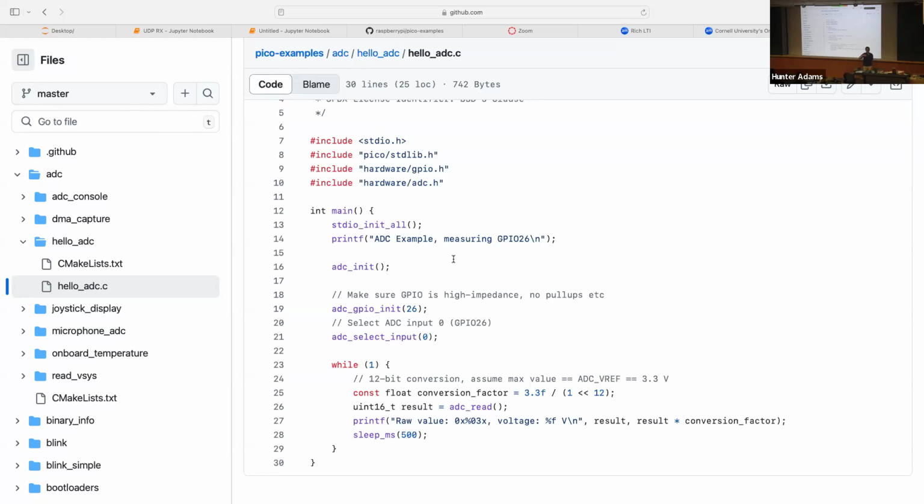And that's sort of expected because remember when we talked about the ADC, one of the things that we discussed was though this is a 12-bit analog to digital converter, your effective number of bits is 8.7. So what that suggests is that the bottom 3 to 4 bits are very, very noisy. And so even when the voltage coming into the analog input is not changing, you're going to see some noise in the least significant 3 or 4 bits of that ADC. So how do you handle this?